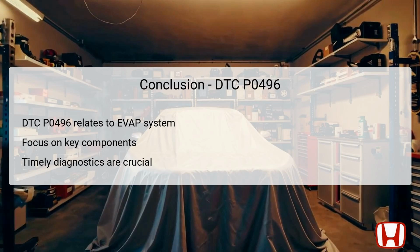In summary, the DTC P0496 code highlights a high purge flow condition within the EVAP system of the 2006 to 2011 Honda Civic. Understanding the key components involved, such as the EVAP canister purge valve and the FTP sensor, is critical for effective troubleshooting.